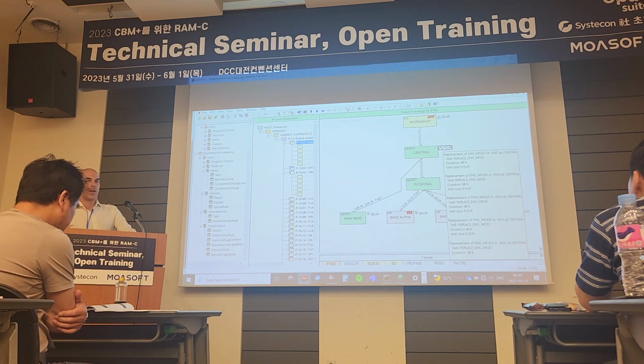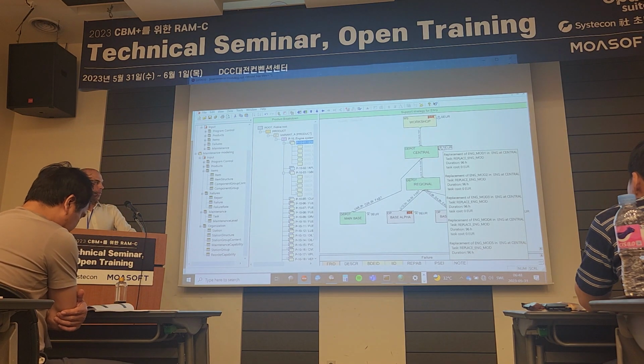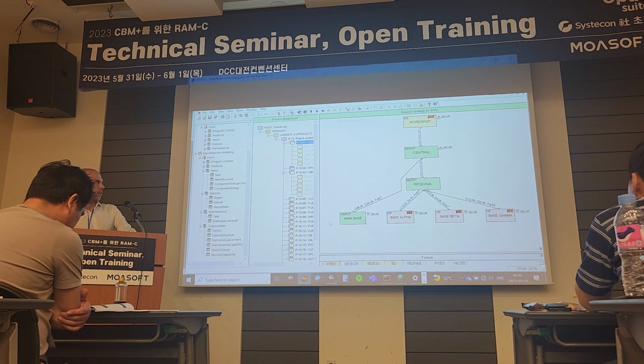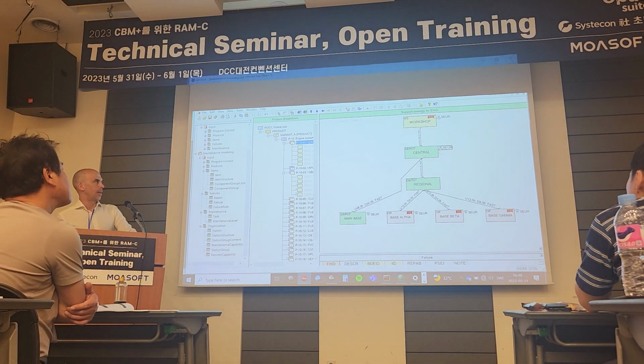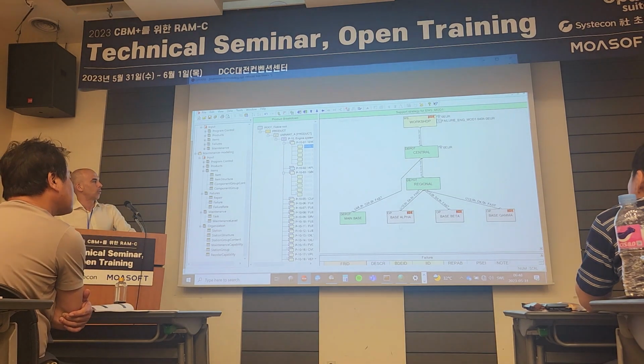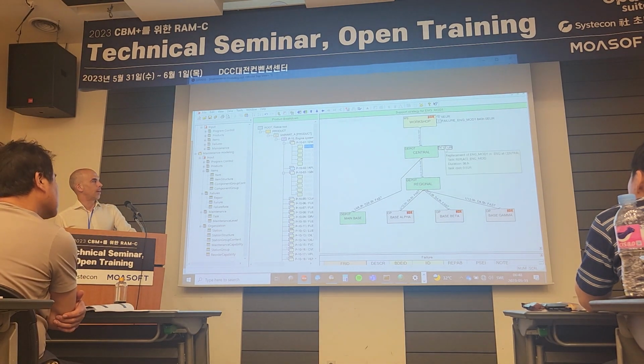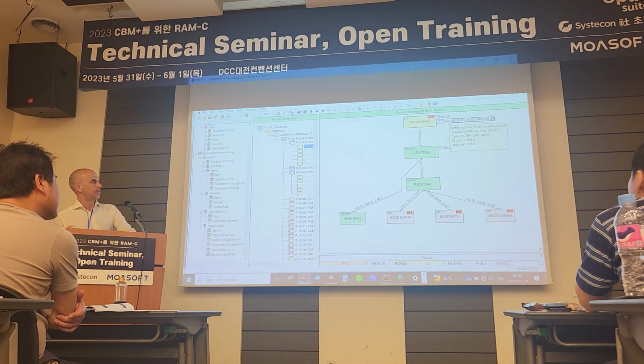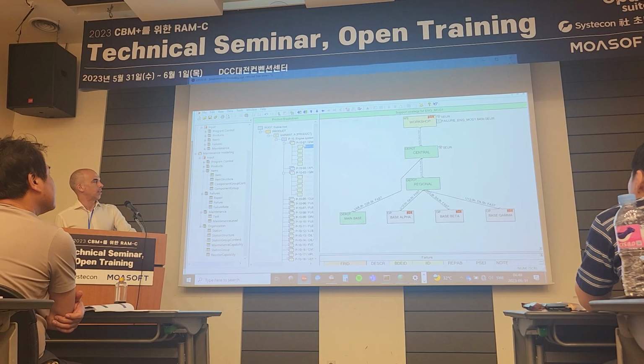But this is the policy for the engine: removal of engine down here, removal of engine module here, and repair of engine module. If I check the engine module, you see it's removed here and repaired up here. And if I take the engine primary item, removed here, remove module here, and yeah, typically it's possible to remove the modules there as well.